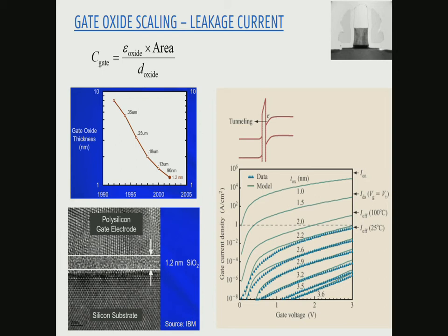And you can see here, this is the oxide thickness, and then the tunneling current. For an oxide thickness of 3.5 or 3.2 nanometer, there's not a lot of issue, but once you start to get to 2 nanometers or 1.5 or 1 nanometer, you start to end up with thousands of amps per square centimeter leakage current, which meant that this was simply not useful.